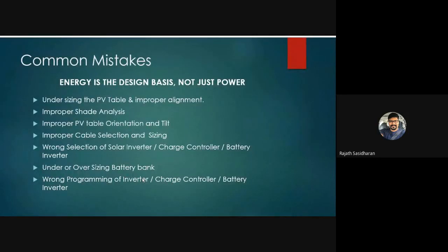Some of the common mistakes: energy is the design basis, ladies and gentlemen. Whenever we talk photovoltaics, we talk energy, not just power, because say if your house demand load is 10 kilowatts, then putting in a 10 kilowatt solar photovoltaic system will not work because there are several variables associated. Probably you'll have to go for 30 kilowatt or even 35 kilowatt to cater to a 10 kilowatt load, depending on what kind of system it is and your weather and the orientation, the location of the building, etc. So always, energy is the design basis, and I've explained how to calculate the energy consumed by your house.